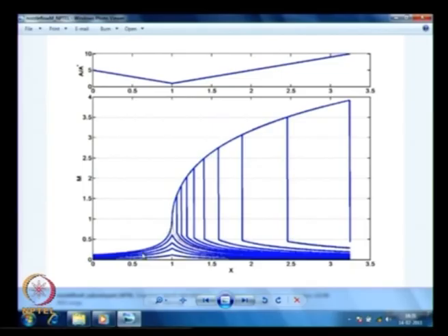Okay. If I go anything below that pressure, my Mach number increases, it goes supersonic, jumps across the shock to subsonic. So you can see that M equal to 1 line is here, it is jumping across from there to here to subsonic, and then it is going subsonic solution, decreasing Mach number further.